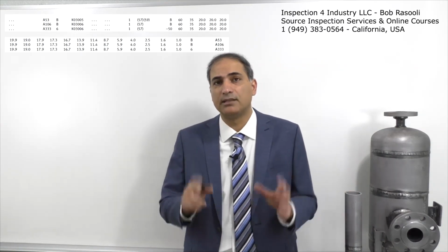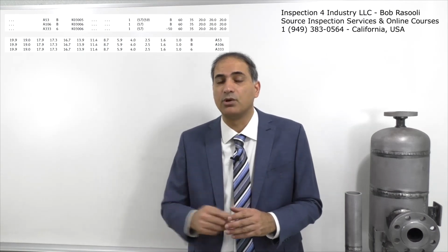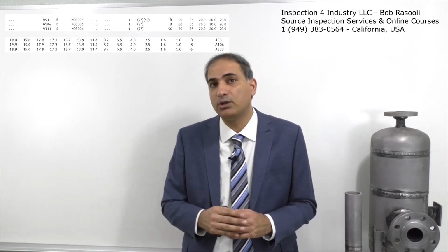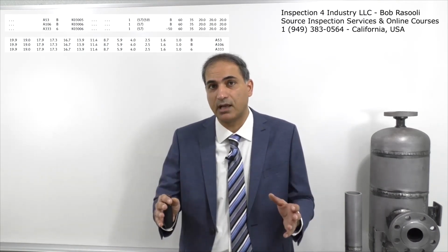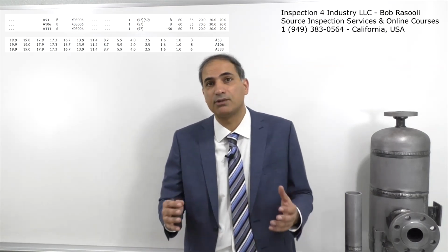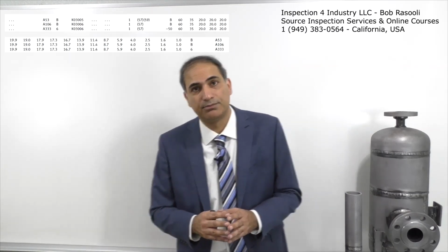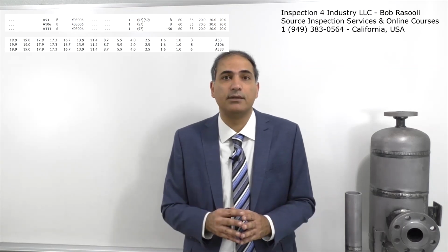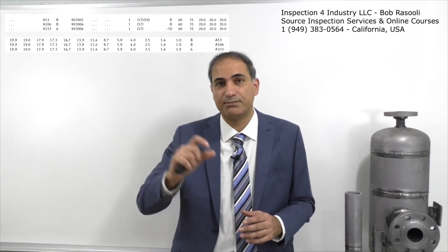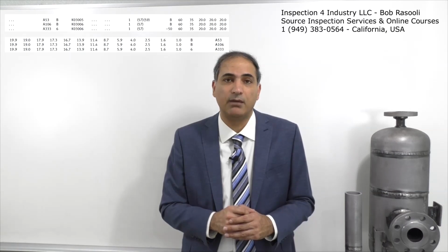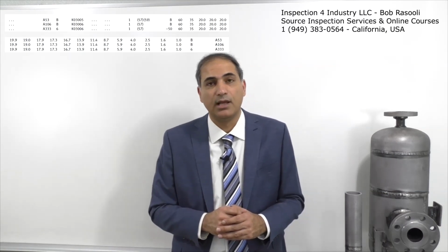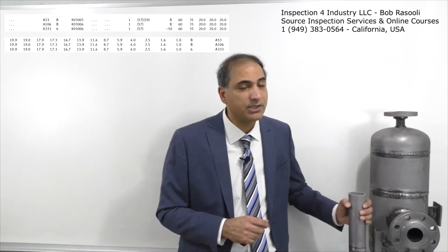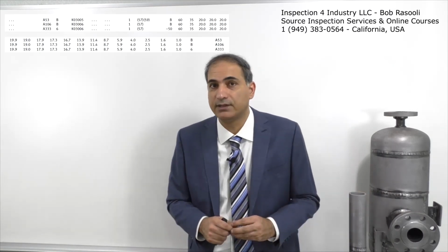So I'm not sure, but I think it's going to be 20,000 psi. So what was your yield point? It was 35,000 psi. So it's like 20,000 psi, probably. Then you have a lot of difference between your allowable stress and the yield point, and that's why the allowable stress is also different at a different temperature.